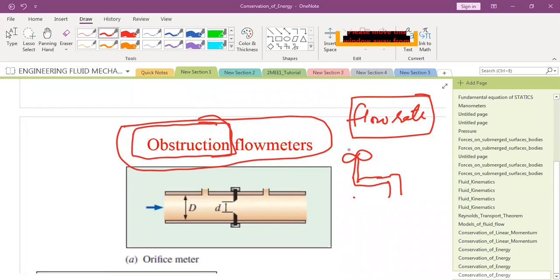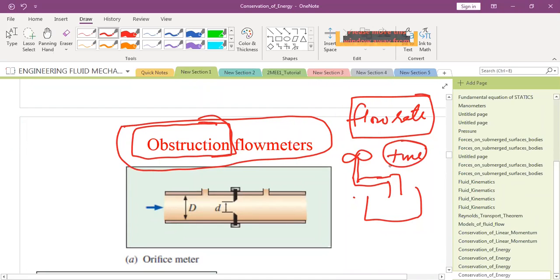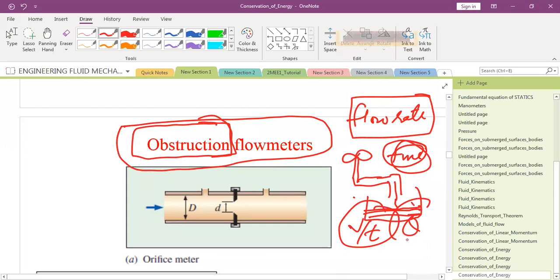Sir, we will turn the tap on, note the time corresponding to the amount of water that comes out, and from that the flow rate will come. Okay, so you will keep a stopwatch or a simple watch. So you will see how much water fills up, and you will note the time. So volume upon time elapsed will give you the flow rate.